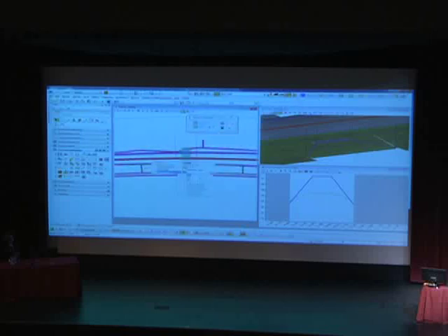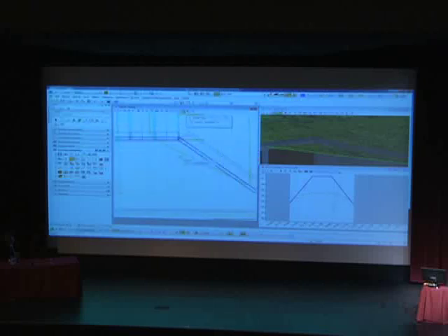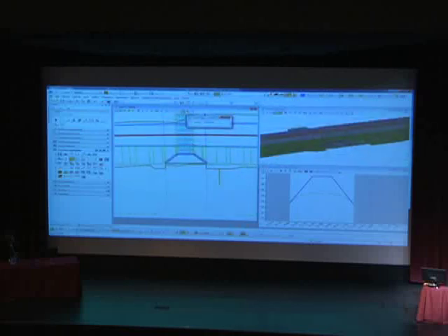And now that the templates get dropped, it's going to clean up a lot nicer. So there you go. Now you still have those key areas that are still a little messy, and you're like, oh man, I need a template right here. So you use a tool called key stations. I clicked that, and then I clicked the location I want, and now it's cleaned up. So I went in, and there you go. I have the culvert already in place and the head wall set up.